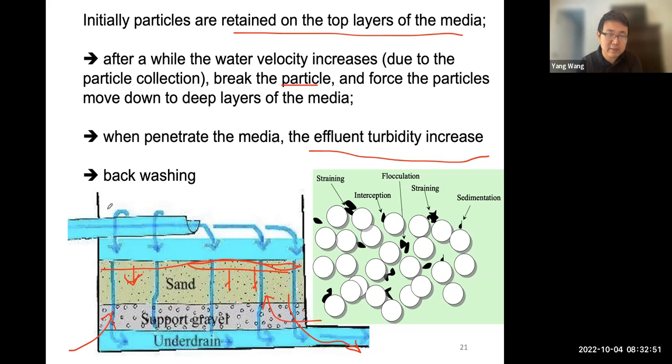So basically what we do is shut off this inlet or inflow here, and then create an effluent on the top. The backwash water is going to bring all the particles, flush them out, and carry them to the effluent. In this way, you can remove the particles that are already in the sand, regenerate the sand filter, and then it can get back online.